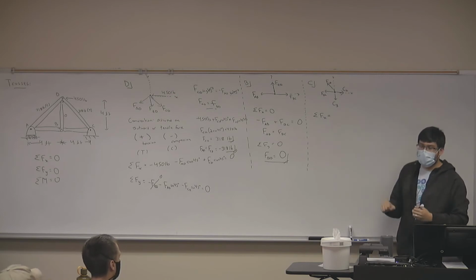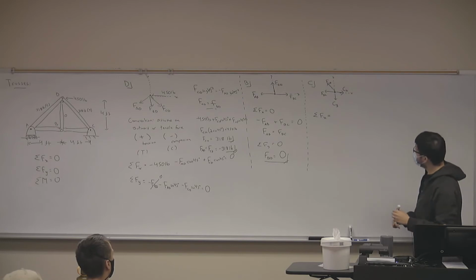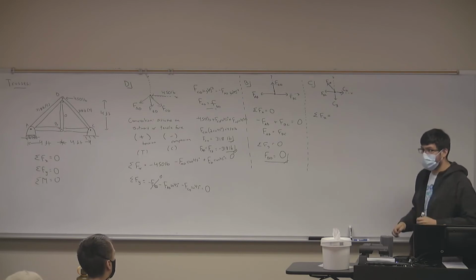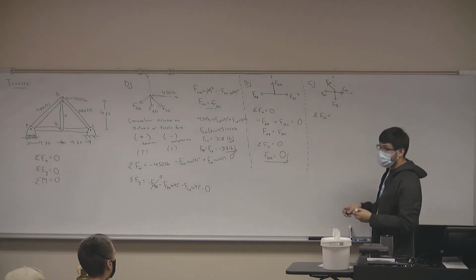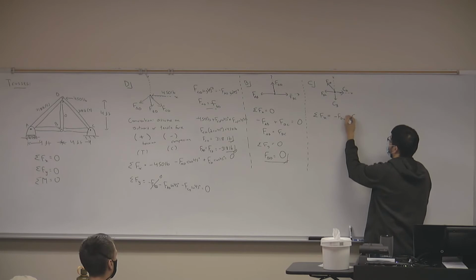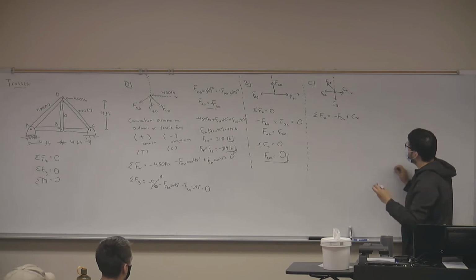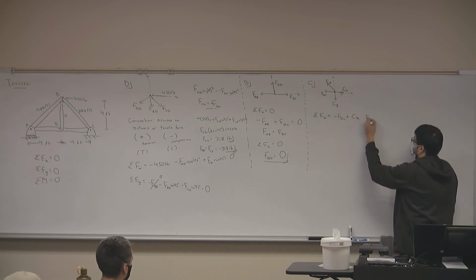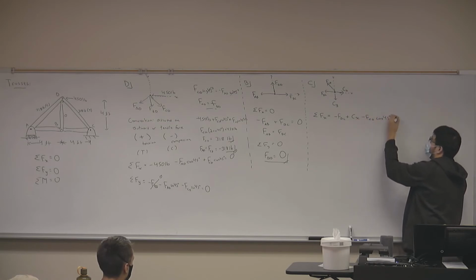So, what do we have in the x direction? Is it the force in the x direction? Yeah, which forces do we have in the x direction? FBC minus FCx equals 0. Or, no, sorry, plus. There we go. Are those the only forces we have in the x direction? What am I missing? FCD, the cosine of the CD force. Exactly. Minus FCD times cosine of what? 45 degrees. That's correct.